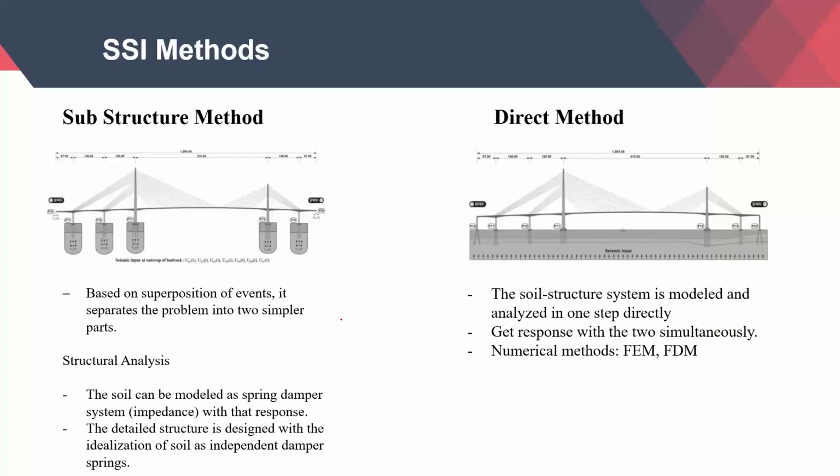So based on that, you will get your p-y curve for every node you have created along the length of the pile. Now we come to the direct method. So in today's session, we will cover the direct method.